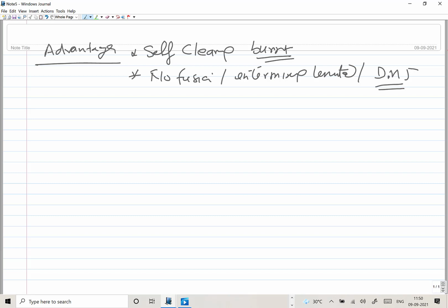welding. Okay. Further, it may be very cost effective also, in the sense that there is no use of filler, except when you are working with dissimilar metals, or you have to bring in a third metal in order to deal with metallurgical compatibility or thermal expansion coefficient related issues. There is no filler, or you can use an interlayer also, but in very few cases.